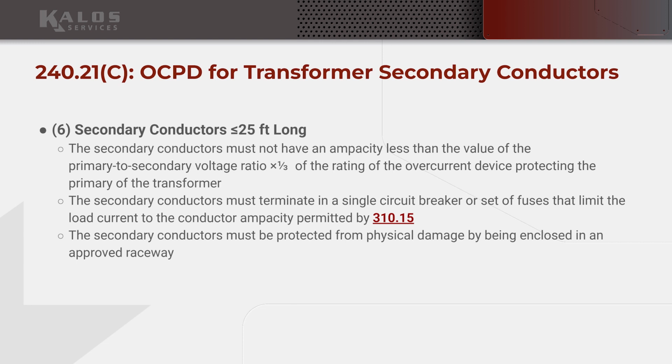This is something that I'm pretty confident we've missed on several projects because we just follow the design. But honestly, we could RFI this, right? And then the engineer is going to say one or two things. He'll say, okay, well, let's put a fuse disconnect within 10 feet. Well, that's going to result in a change order for us because it's a design change.